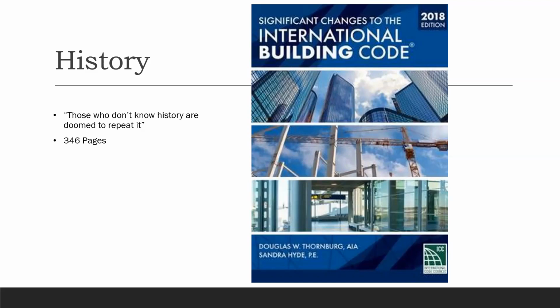Here I have an example for you. It's on page 182, and it says basically, because so many fire deaths are occurring because people are asleep at the time of a fire, they're requiring sleeping rooms below the 4th story to have windows or doors to be used for emergency escape or rescue. Why do I share that with you? Well, the point is that as our information, knowledge, and the statistics that we find are evolving about fires and about smoke, the code is evolving with it, and we're adapting to that necessary change.